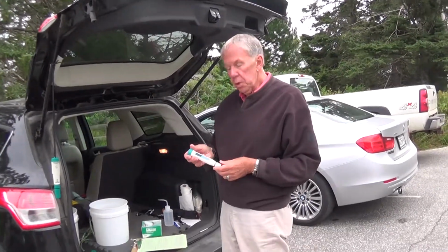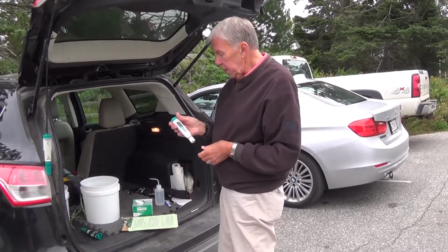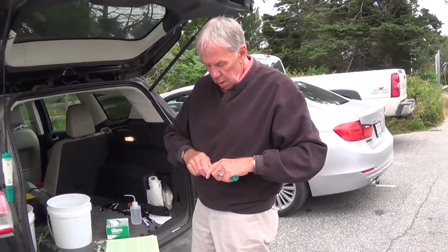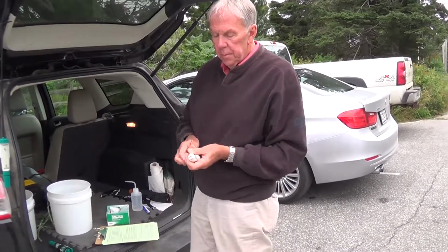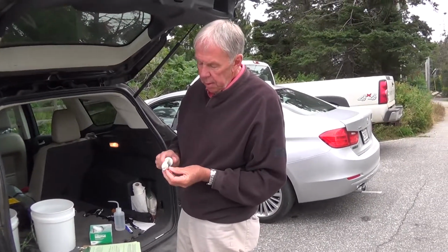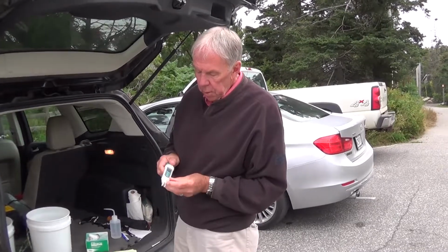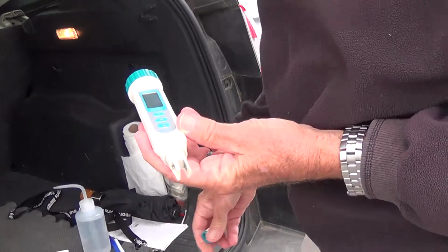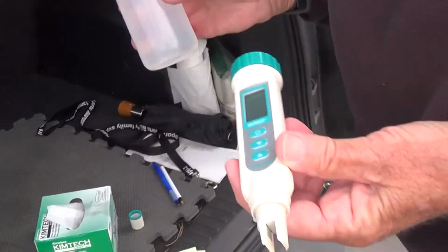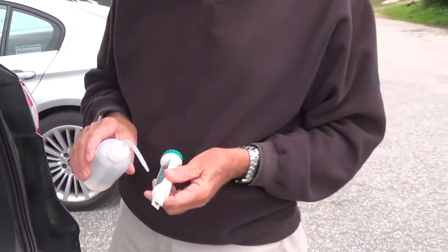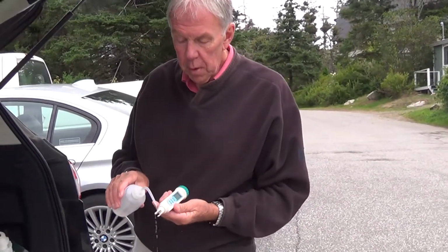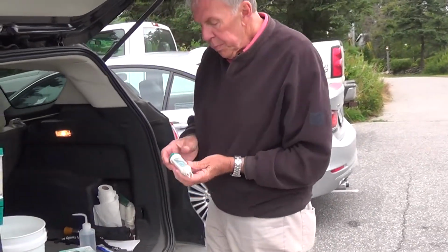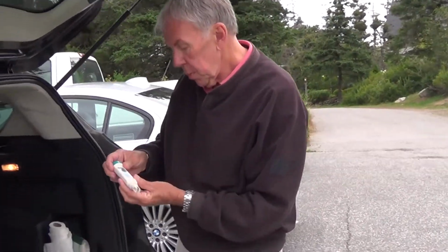So, the first test we're going to do is for salinity, and here is the meter. You want to carefully remove this cover. So these are the electrodes. You want to be careful. You don't really need to touch those. One thing I always do, it may not be called for in the directions, but I always rinse these off. This is distilled water, just in case there was any contamination. Then you turn it on,